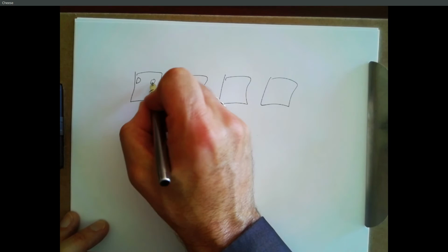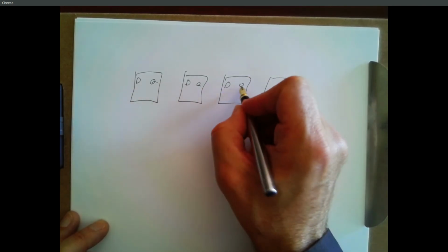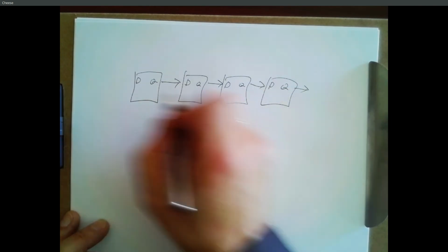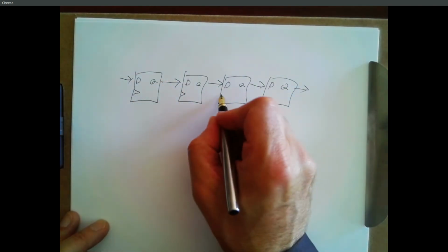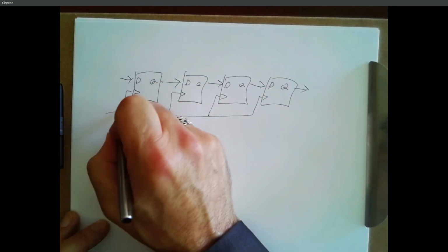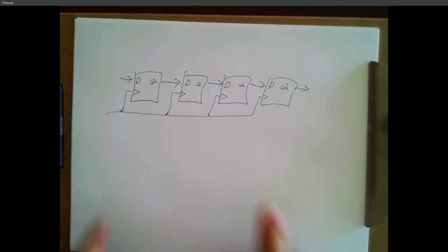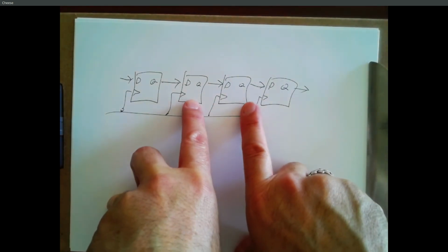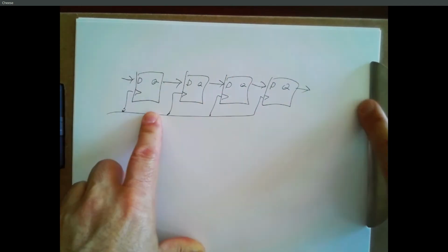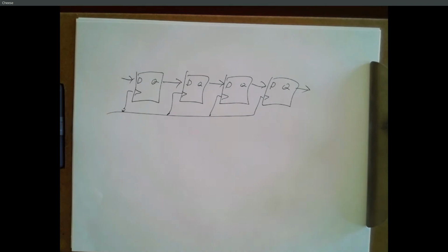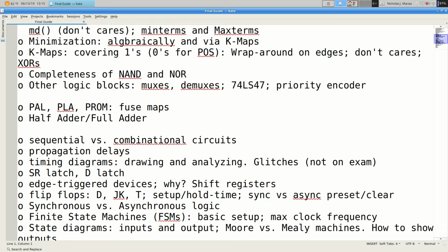Right, if these are D flip-flops, and your clocks are all tied together, then when the clock ticks, everything moves down one spot. Right, if these were level triggered devices, as soon as I raise this, everything races through all the way. Right, so that was that I equals I plus 1 that just kept counting in the beginning of talking about sequential elements.